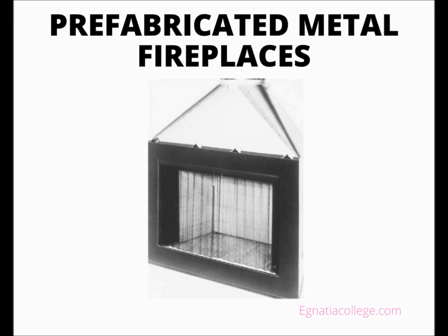Engineered, metal fireboxes have been developed that can be installed in very little time and require only modest foundations. The prefabricated units are available from several manufacturers and in a variety of styles. However, they are all similar in that they have double walls and a complete throat with the damper in place. Most also have a fire brick floor.